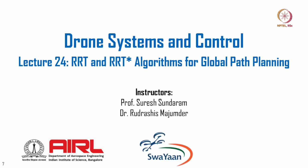In the last lecture we have gone through A star algorithm and we have seen how it can be used for global path planning. However, we were mentioning some limitations. We will have a recap on those limitations of A star algorithm, and in this lecture the main focus is on RRT and RRT star algorithms for global path planning.